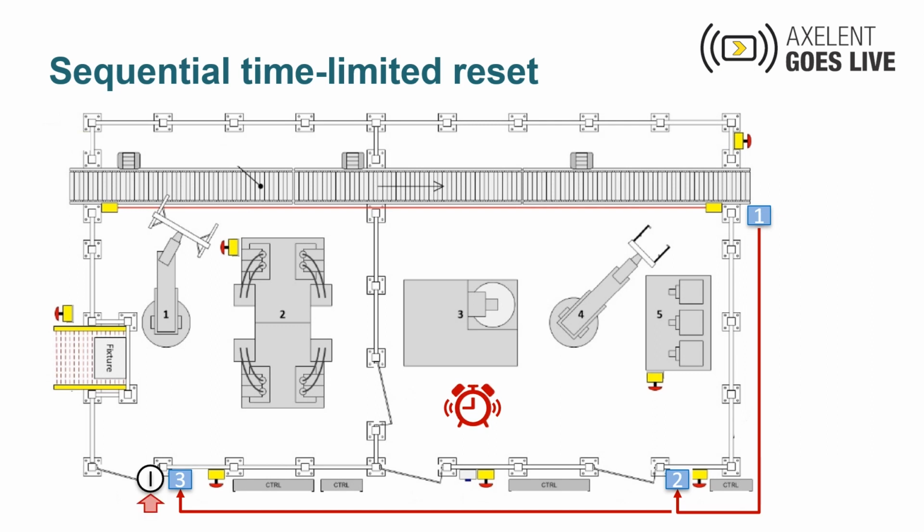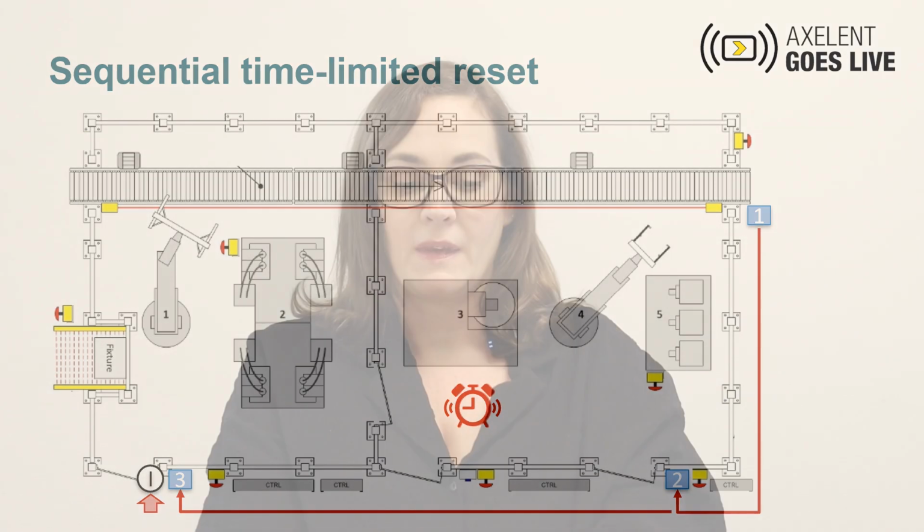What's the point of that? The point of that is to make the operator walk alongside the system and look inside to check if somebody's in there still. And making him press several buttons in a row will ensure that he has looked at every section, every portion of the system before he starts it. That seems like a clever setup.